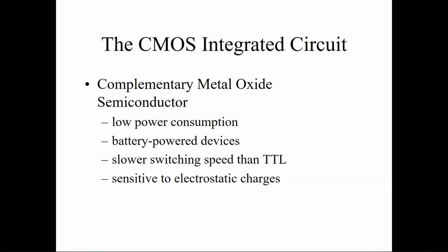Make sure the power's off. Well, you need to make sure your power's off, but you also need to make sure that you do not carry any static electricity. Because believe you me, static electricity can and does kill any and all electronics if you are not careful about how much you carry on you. You have to remember, guys, whenever you're dealing with IC chips and stuff, these are very delicately balanced so that they work correctly and most efficiently. But at the same time, if you have any transient voltages sticking to you, which this time of year we generally have a lot of, right?